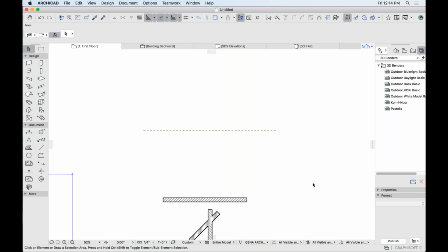And I could also actually print this guideline too. So we go from the snap guides, the blue ones, which are really temporary, to the orange guidelines that are semi-permanent. And then we move off to just using regular lines if you want to have something that is permanent, that you can turn on and off, that you can refer to over and over and over again throughout your project.